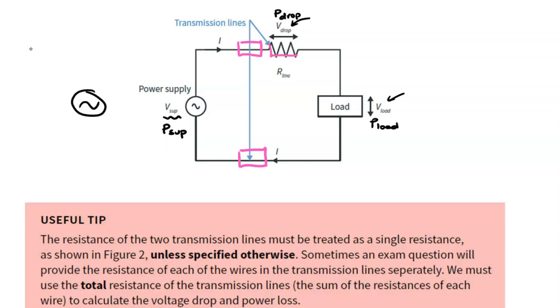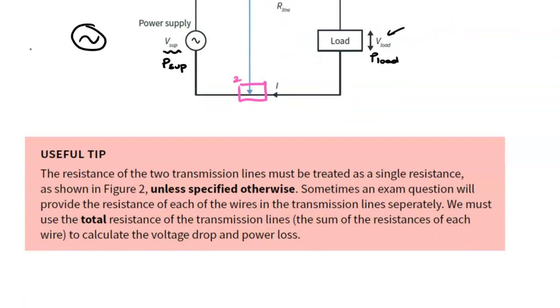That's the old-fashioned way of representing a resistor, just so you know. There's two ways, the box or the zigzag. Those two resistors would be in series, and in series we add resistances. So R series, if we called this 1 and 2, it'd just be R1 plus R2. In parallel, it's a little more complex, but in series you just add them together. So that's what this is talking about here.